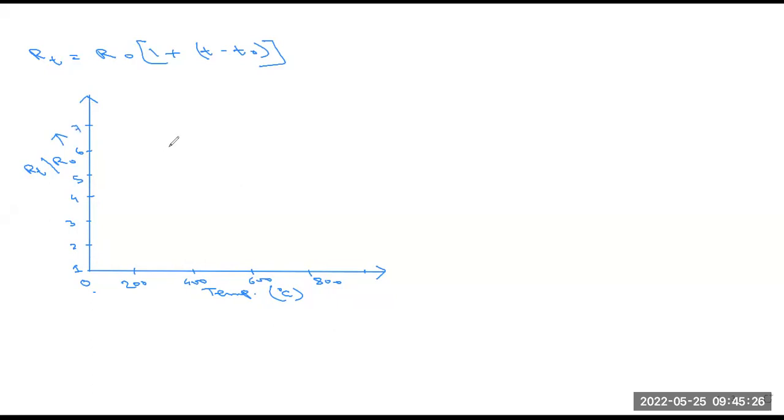So we have to express here three types of material, which we use for our RTD temperature devices: platinum, copper, and nickel. Platinum is basically costlier than nickel and copper. When you use platinum material, it gives a more stable result, almost like a straight line.